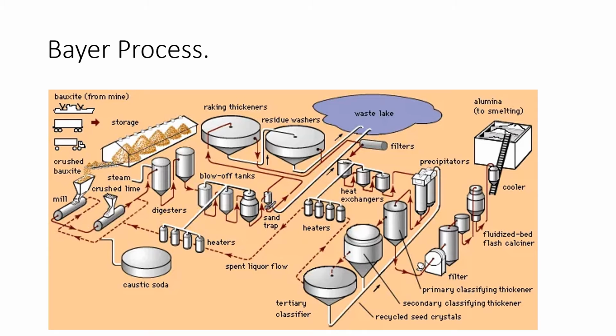Sizable amounts of aluminum hydroxide crystals are added to the solution in the precipitators as seeding to hasten crystal separation. The seed crystals attract other crystals and form agglomerates. These are classified into larger product size materials and finer materials that are recycled as seeds.